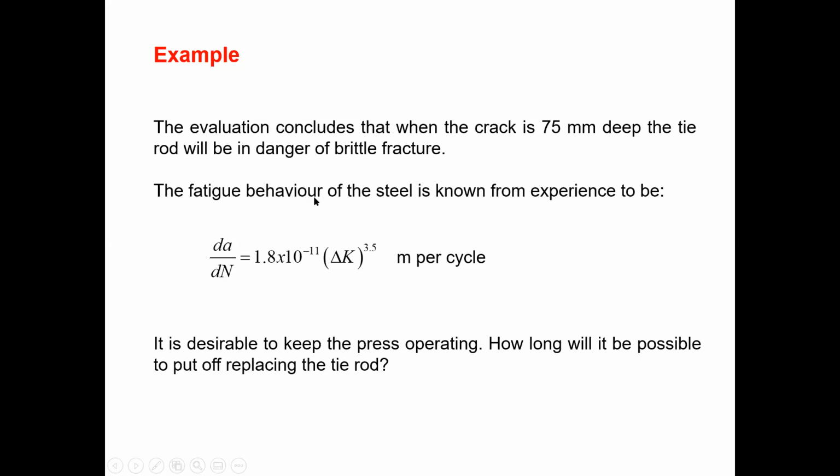The fatigue behavior of the steel is known from experience to be, and they provide the C and M. You can see this is C, this is M, in the Paris equation. They provide the two constants. I told you they will provide the units, you don't worry about it.